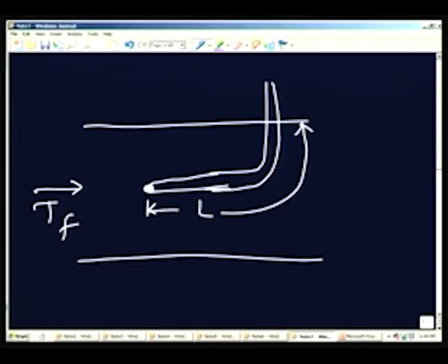So, if I make it long in this direction and then with a 90-degree bend here, the output is going to be measured there. This is connected to the voltmeter, and I have a very long length. Okay. So, the length of the immersion is an important parameter which is going to play an important role in determining the size of the error, and therefore, there is one thing which we are going to look at.